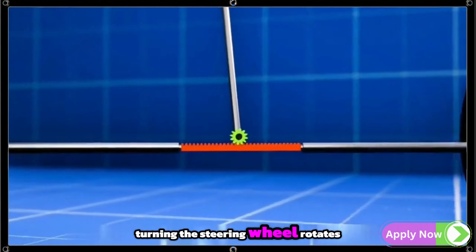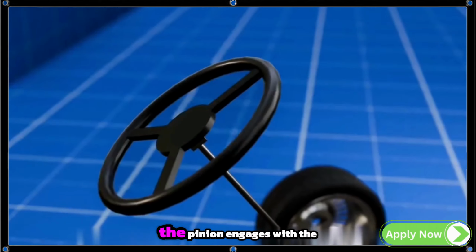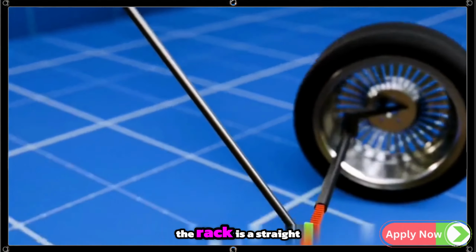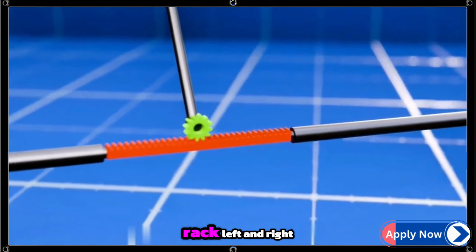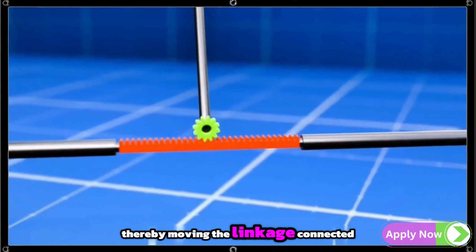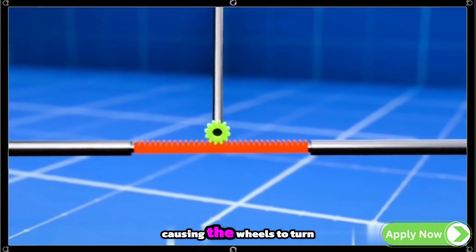Turning the steering wheel rotates the shaft connected to the pinion. The pinion engages with the rack. The rack is a straight rod with teeth. When the pinion rotates, it pushes or pulls the rack left and right, thereby moving the linkage connected to the wheels, causing the wheels to turn.